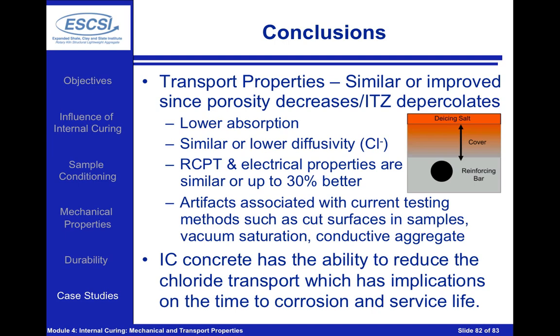We need to be very careful if we start replacing large volumes of the aggregate because the conductivity can actually change some of our electrical measurements. But in general, for internally cured concretes, our current recommendation is to test them the same way as conventional concretes and to ignore the effects of the conductive aggregate, and we're going to be conservative in doing that.